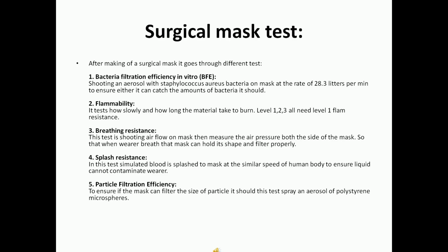4. Splash resistance. In this test, simulated blood is splashed at the mask at a speed similar to that of the human body to ensure liquid cannot contaminate the wearer. 5. Particle filtration efficiency. To ensure the mask can filter the size of particle it should, this test sprays an aerosol of polystyrene microspheres.